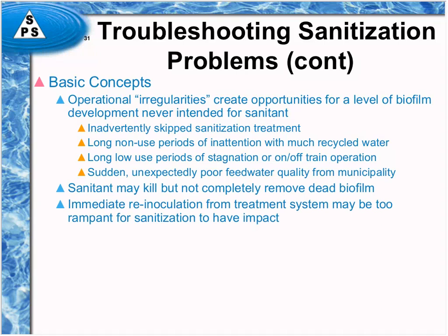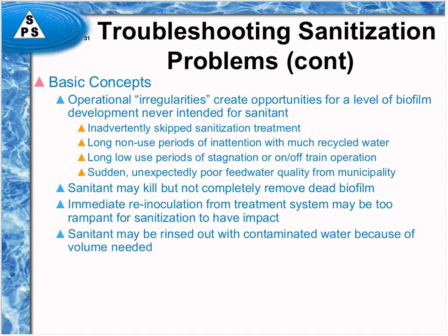You may see that there's such immediate reinoculation after the system's been sanitized that the sanitization is having almost no effect, because there's a lot of high levels of organisms coming into the system brand new. The sanitant may need to be rinsed out of the system after the treatment, but make sure you don't use contaminated water to do it. I mean, heavens, it's just common sense to use good water to clean out a sanitant and not just reinoculate the system with contaminated water. So you've got to plan ahead for that and design ahead for that to make sure you have saved up enough good water to use for rinsing.